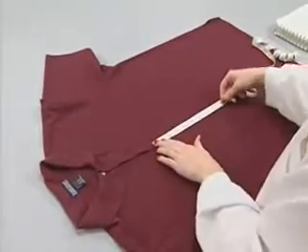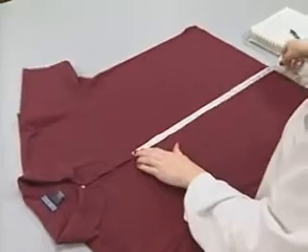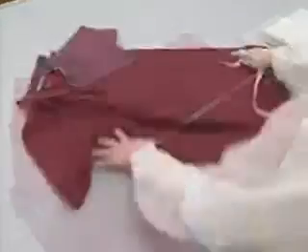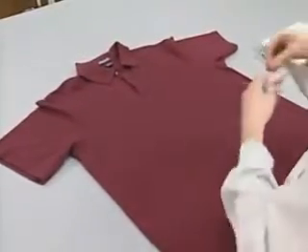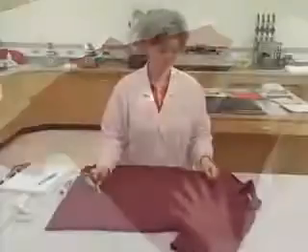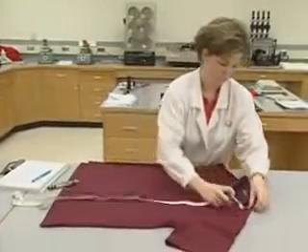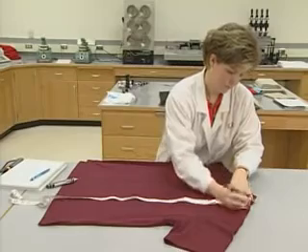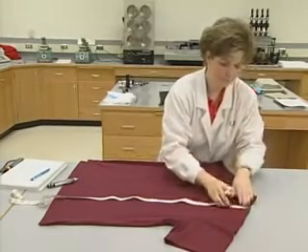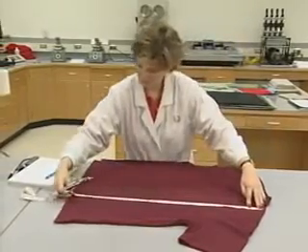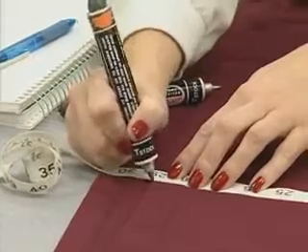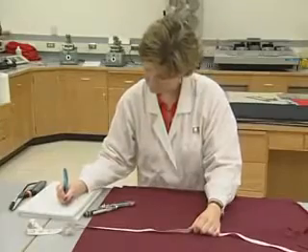In the basic method, a knit shirt is laid on a table and all folds and wrinkles are carefully spread out on the table with the front of the shirt facing up. For shrinkage measurements, the shirt is marked and measured at several locations before and after laundering. The benchmark for length shrinkage is determined by measuring from where the collar is sewn into the shirt at the junction of the shoulder seam. A mark is made at this point, and a tape measure is stretched from this point directly down to the bottom edge of the waist hem. A mark is made at this point, and the length is recorded to the 1/10 of an inch.